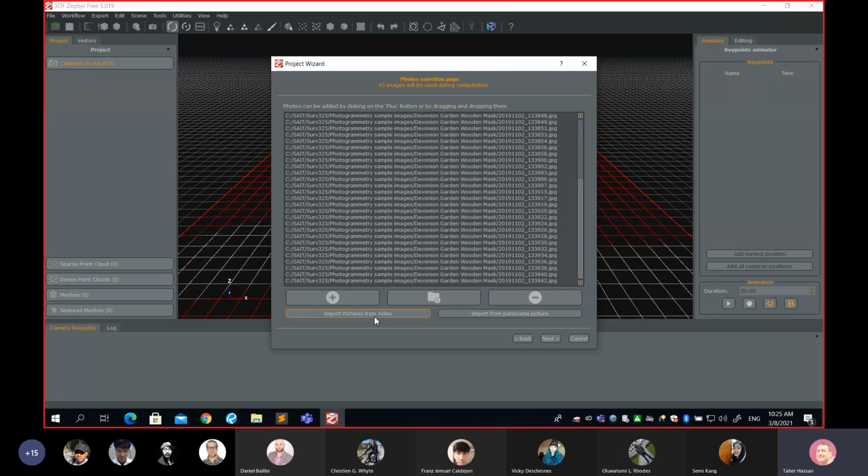Remember, as I said before, we need at least two images. Those two images must have a spacing. Look at your eyes. You have two eyes, and there is a space in between them. This already has a name: the base of photography. If this base is so tiny, it doesn't help you create a good 3D model. That's why when you pick frames from a video, you have to be very careful. You have to leave some time until you move your camera somewhere, and then you can pick another frame. Does it make sense?